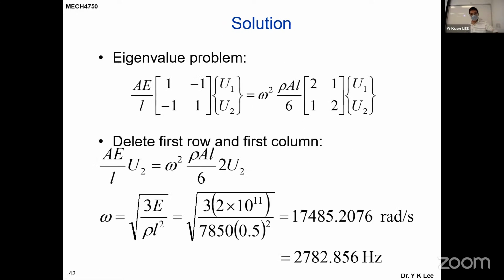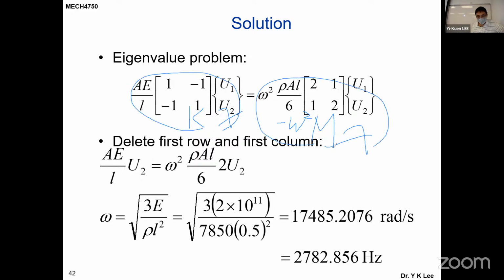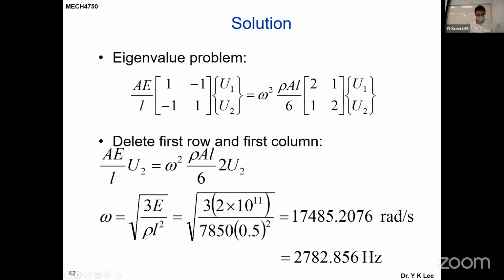So next we can go to the second issue. Why? We have to write our Kx here, and also the inertia minus omega n here. So this one we describe here. Once it is a vibration problem, we have this thing. In this case, we can get this kind of eigenvalue problem, determine our natural frequency, right? So that is something we can easily do. Okay, so this will give you a very simple introduction about this kind of finite element.